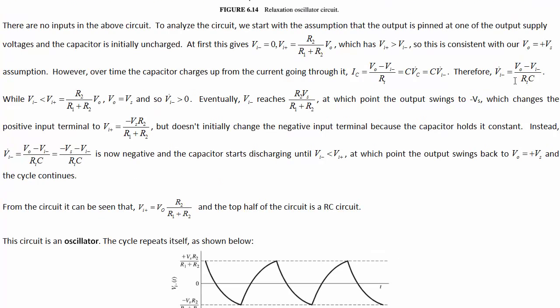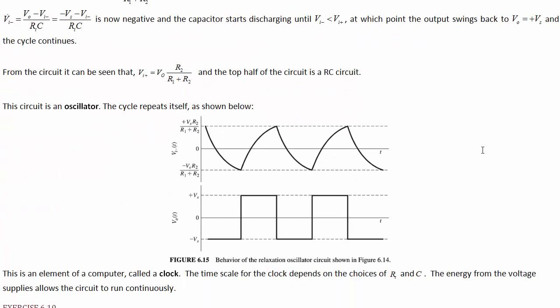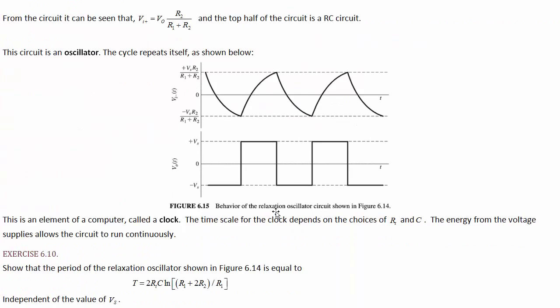It's linear, no sweat. It's not separable, so you just have to use that integrating factor thing and you can solve that all up. Anyway, then once you've solved the differential equation, give it an initial condition of the voltage being this, Vi minus initially is this, and then solve for the time it takes for it to get down to this bottom point.